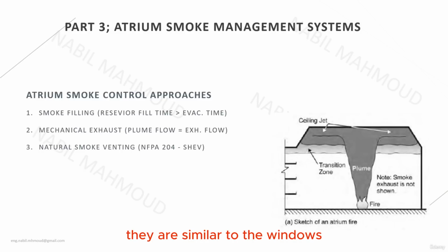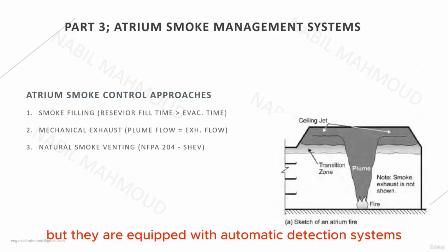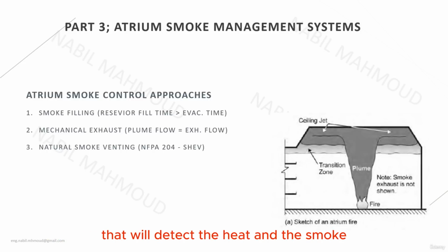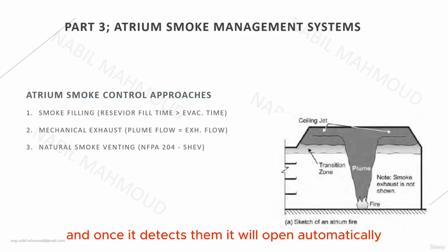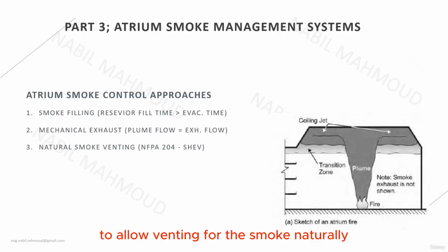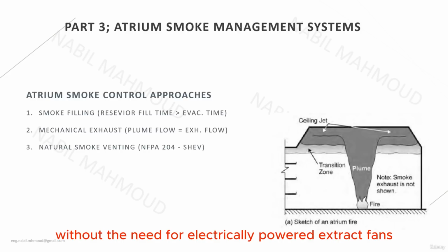They are similar to the windows, but they are equipped with automatic detection systems that will detect the heat and the smoke, and once it detects them, it will open automatically to allow venting for the smoke naturally without the need for electrically powered extract fans.